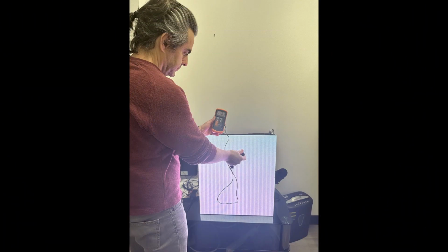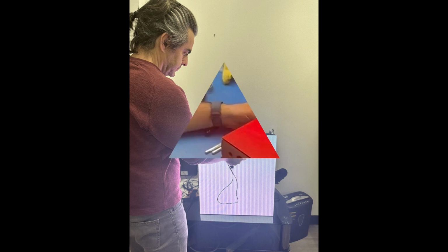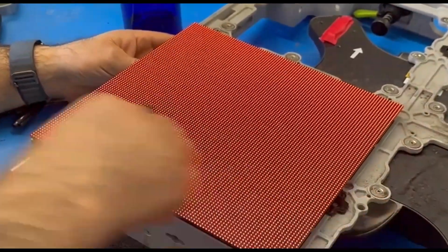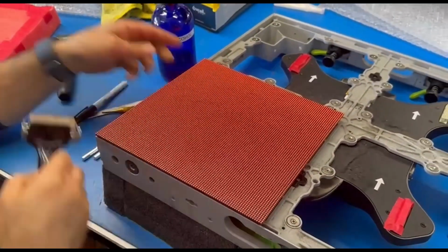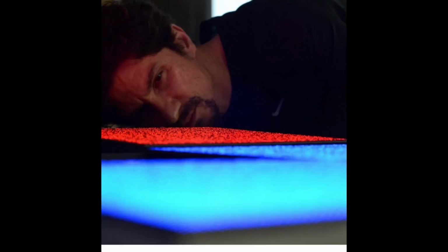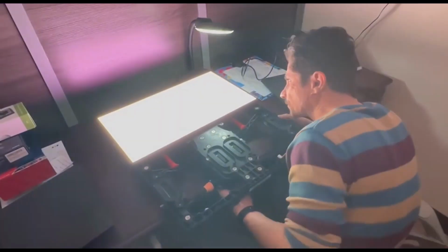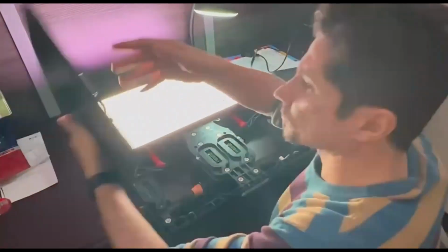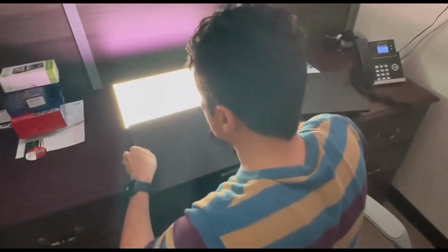At a brightness level of 1200 nits, the X2V produces vivid and bright displays, making it visible even in well-lit indoor areas. This high brightness makes the content stand out, effortlessly grabbing the audience's attention. We found that our test panel achieved 1200 nits as specified in the datasheet. A horizontal viewing angle of 160 degrees and vertical viewing angle of 140 degrees allow the X2V to provide an optimal viewing experience, accommodating viewers seated at a wide variety of different angles relative to the display.